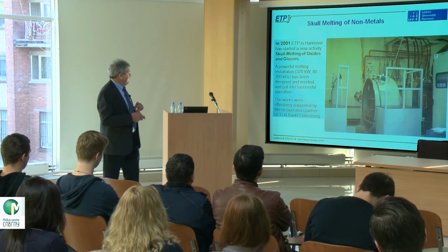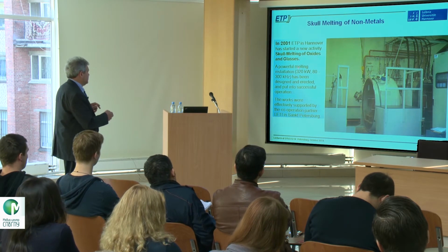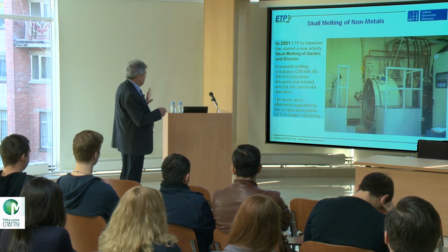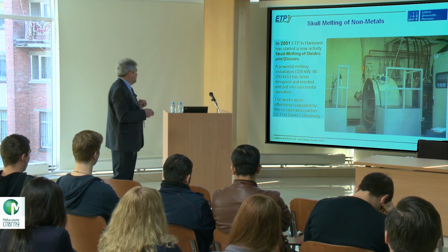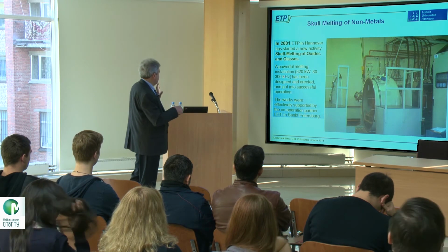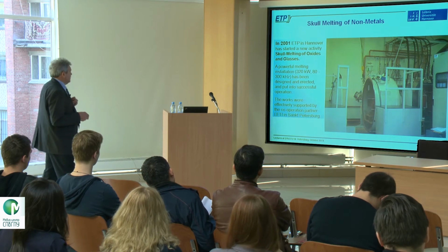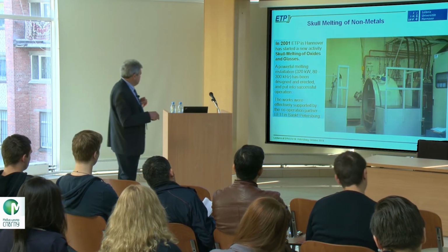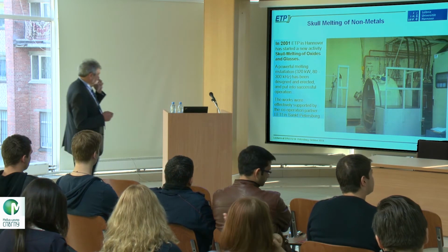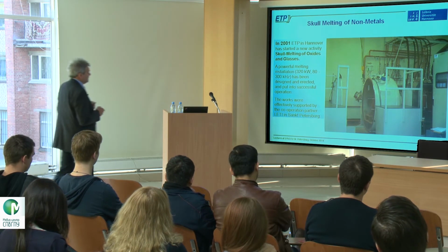So the installation we have installed in Hanover more than 10 years ago. We started in 2003. It went to operation. It's quite powerful, 320 kilowatt. It uses a thyristor and a transistor generator up to 300 kilohertz, and we were supported by our partners later in St. Petersburg, because they had a big knowledge and experience in that.